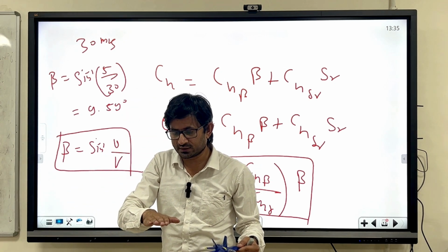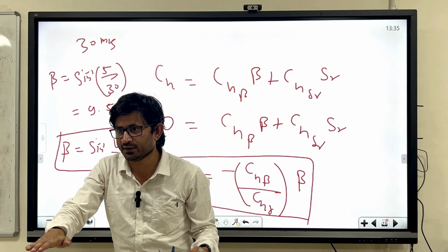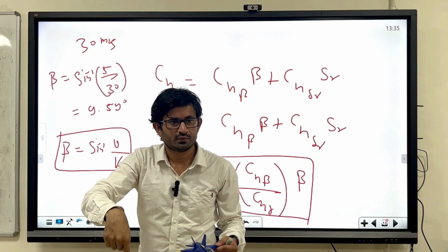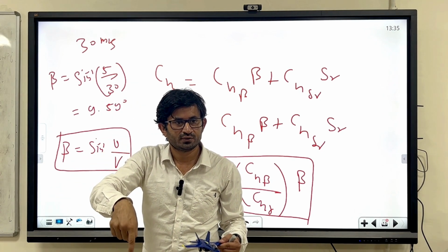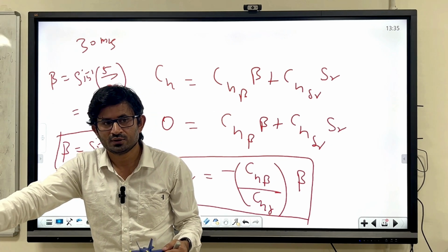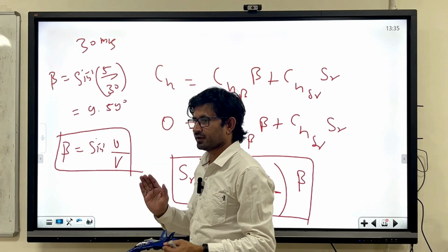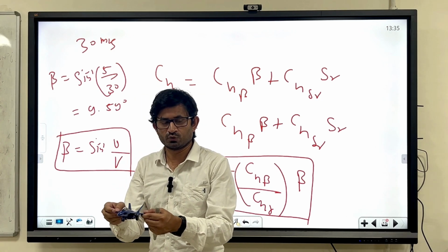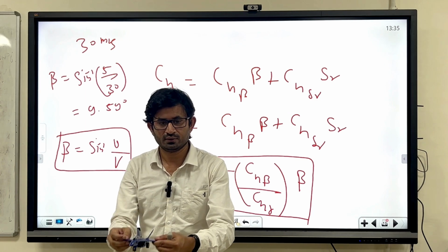If you have the side slip like this and you are landing, then you will not touch down at the landing center point, right? You will skid. But if you deflect the rudder in this direction, which comes to 10 degrees, you will counter the yaw and you can land your aircraft.